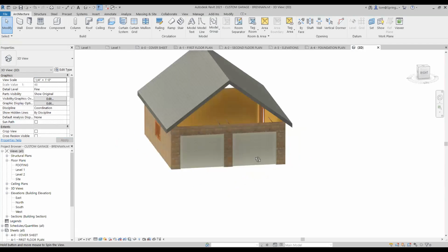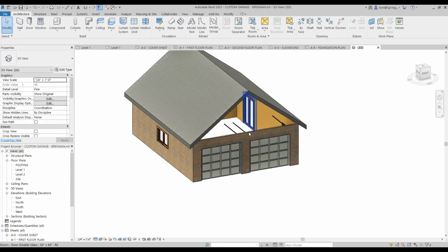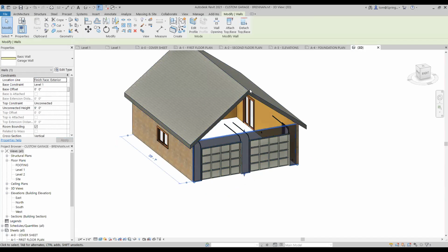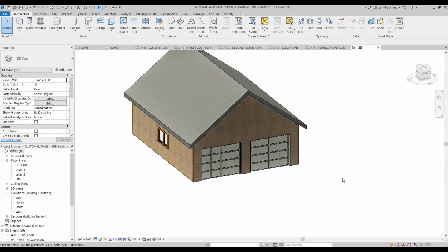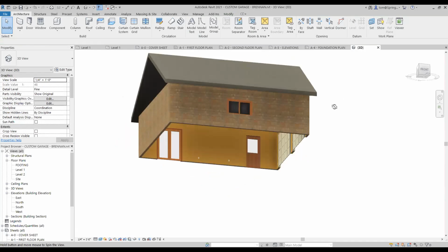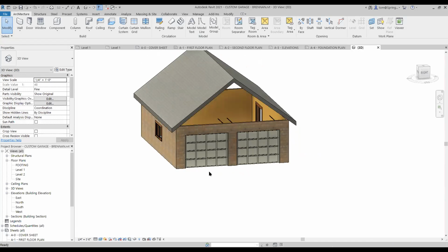And we still have this kind of pesky problem where the walls aren't attached. So I'm going to click on this wall right here, and then there's this great little tool here, attach top base. I click on that and it asks, what do you want to attach to? Well, isn't that easy, okay? So I did that. However, you'll notice that the other walls didn't attach. So I have to go by them one by one, or I can do it this way.